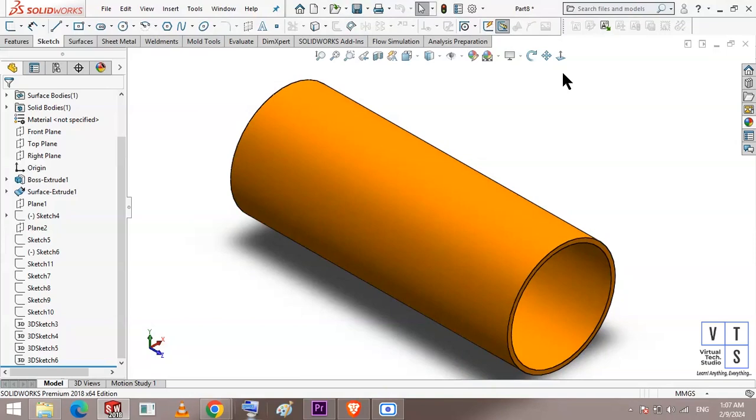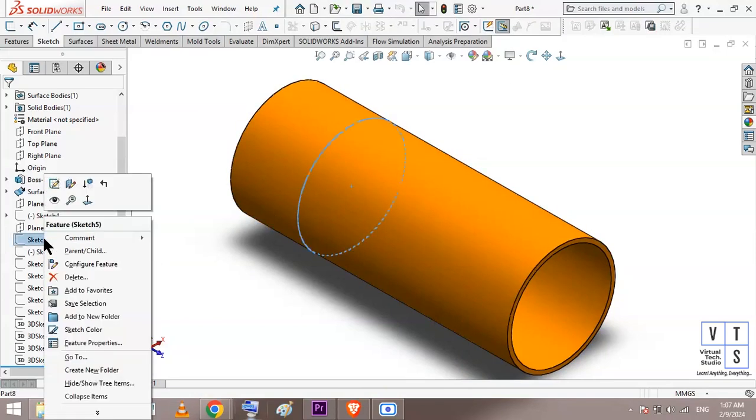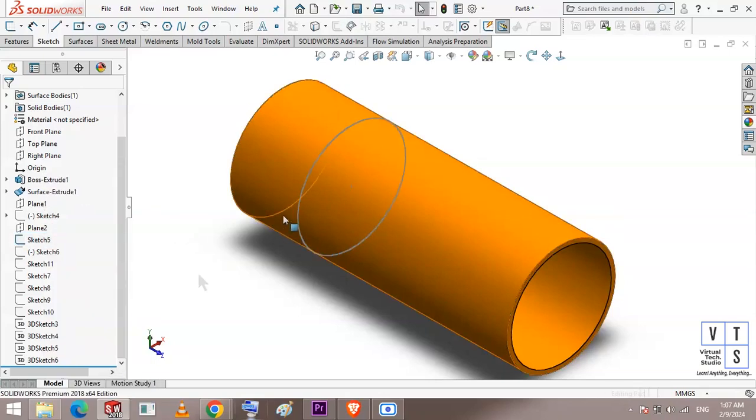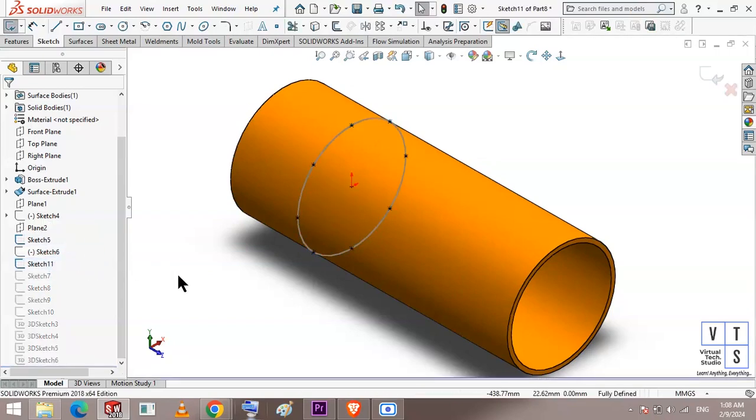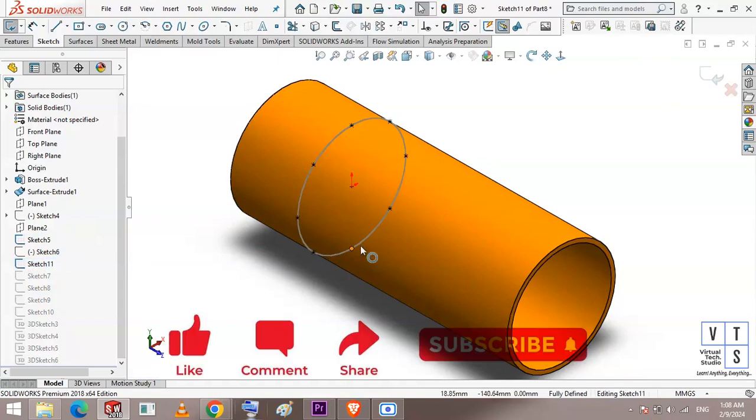Suppose we have a pipe piece at the workshop. First, we have to make a mark at right angle to the longitudinal or lengthwise direction of the pipe, which is obviously a circle. Then we have to divide this circle into some equal segments. The more the segments, the more precise will be our cutting mark. Here we are dividing our circle into 8 equal segments.